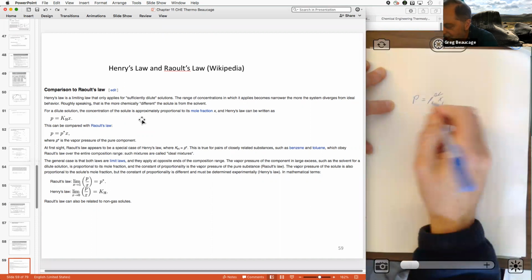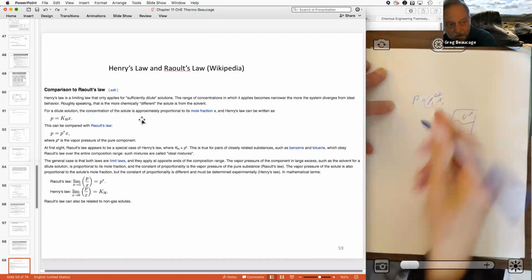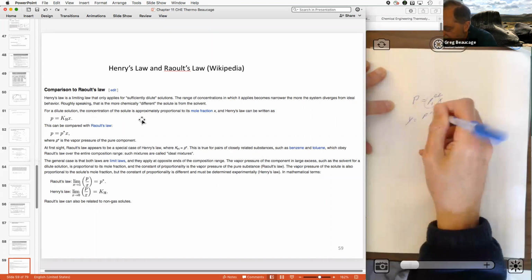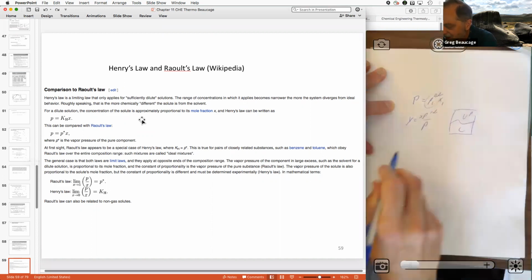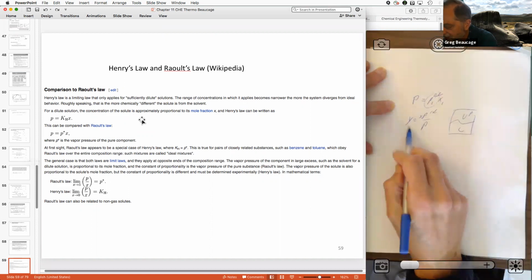You're going to get the pressure from the saturated pressure, right? So in other words, y equals p sat over p times x. That's our base equation that we're using. Right? y over x, the K ratio, is p sat over p.